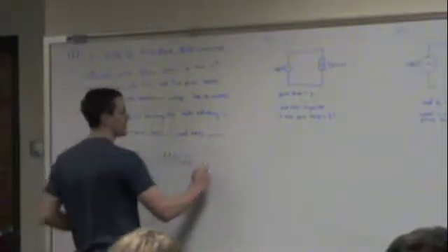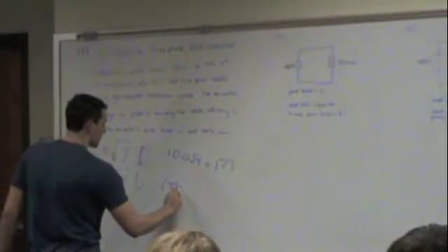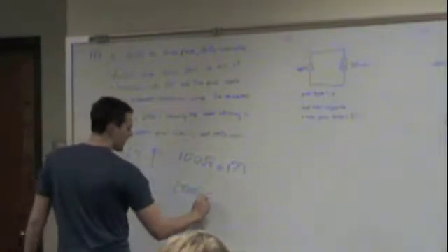So we have these, and then we calculate IL, which is given as 100. So 100 times radical 3. Have you guys memorized radical 3 like I did? 1.73. Yeah, 100 times radical 3 is 173. Fun. And then you come down here, and we know voltage. We know voltage is 2400 times radical 3, which equals 4157.